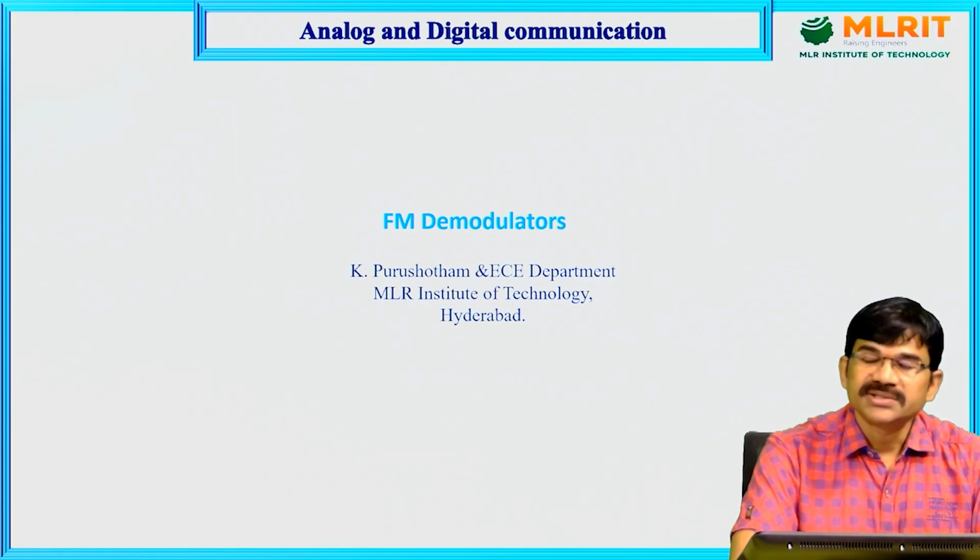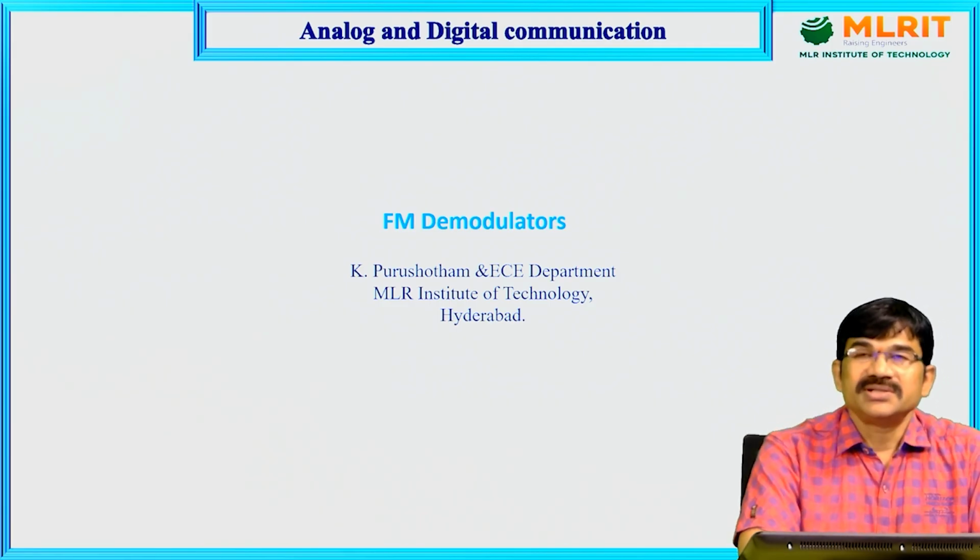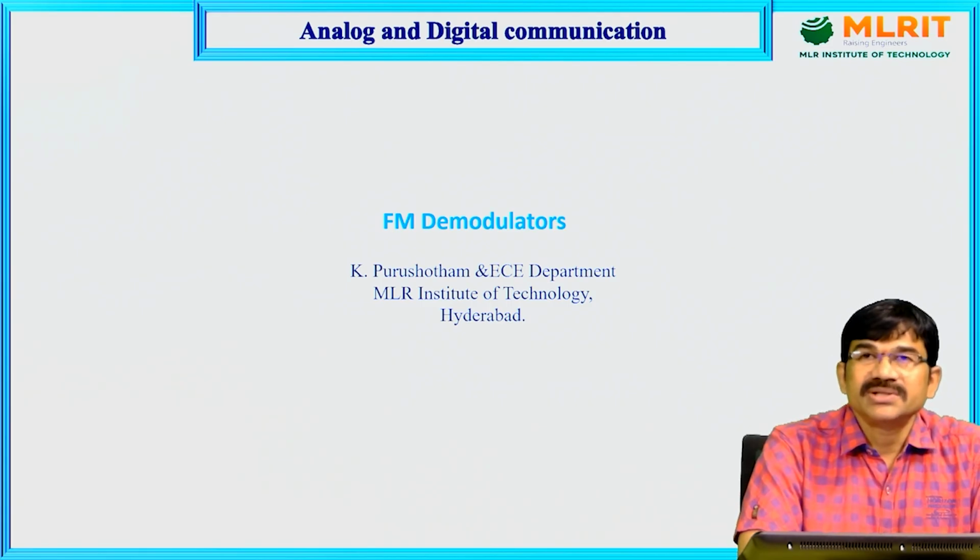In today's lecture we are concentrating on demodulators. What is the function of the demodulator? By using the FM modulator we have modulated the signal and transmitted it. S(t) is the modulated signal which contains the original information and the carrier signal. But at the receiver we want to obtain only the original information.